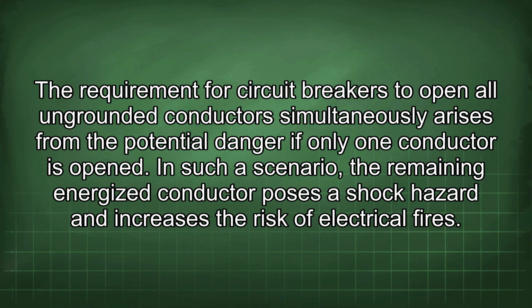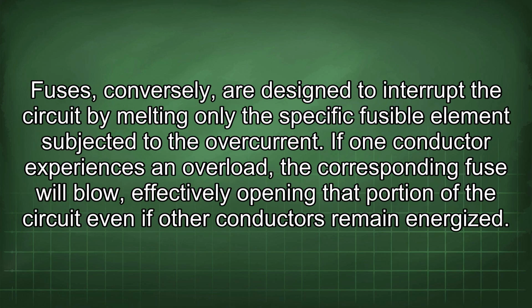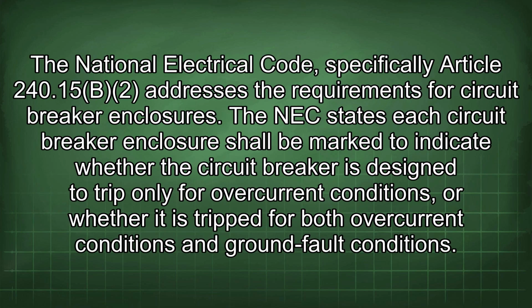In such a scenario, the remaining energized conductor poses a shock hazard and increases the risk of electrical fires. Fuses, conversely, are designed to interrupt the circuit by melting only the specific fusible element subjected to the overcurrent. If one conductor experiences an overload, the corresponding fuse will blow, effectively opening that portion of the circuit even if other conductors remain energized.